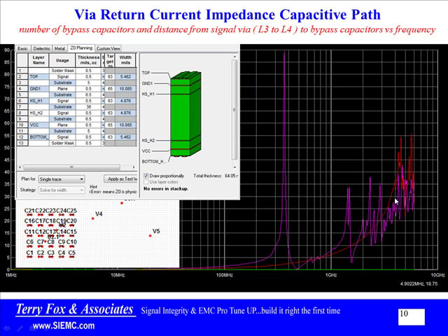So again, when I go through a via, the problem is not, quote, the signal current, because I know where that is. I have intentionally put in that via. The problem is understanding how does the return current move from where it is to where it wants to be.